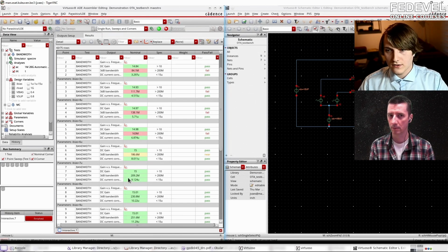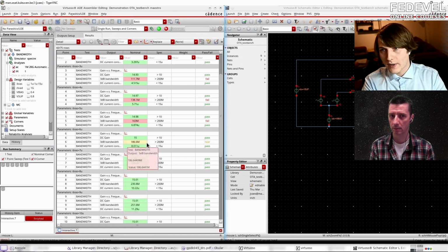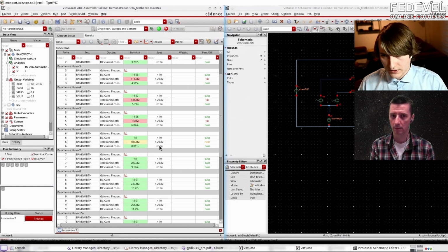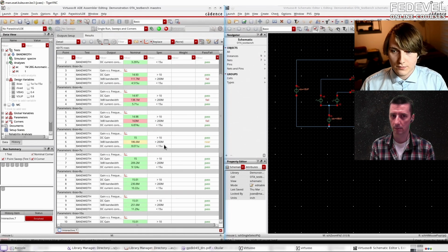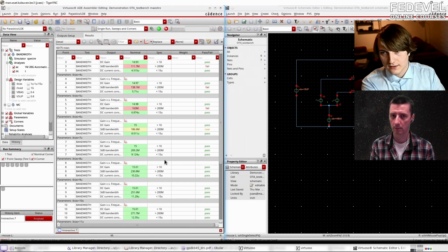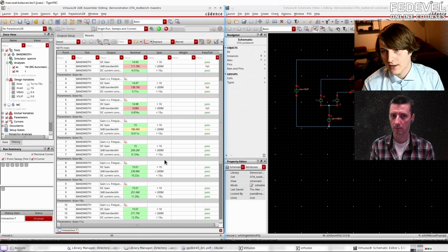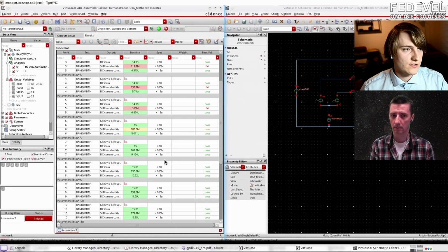And then as a designer, right, based on this, I can now also go back into my cell. I can play around with the transistors, maybe add some more transistors, change the topology and so on. And then I do this for every cell. And this is how we make our design. So we can simulate it in incredible detail because of this, with this PDK and the information in there. And so once I have this in schematic, I can then, for example, send this to a layouter who will then make my layout, or I can make my layout myself. It depends on the company and what you're doing. Yeah, this is the flow for a cell.